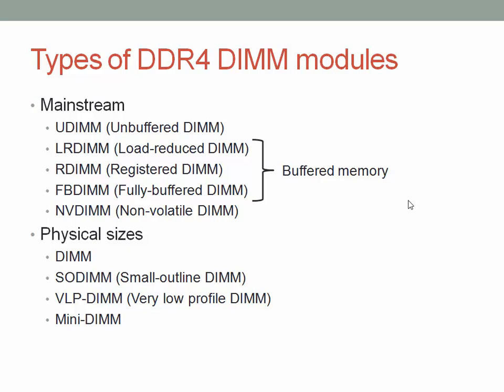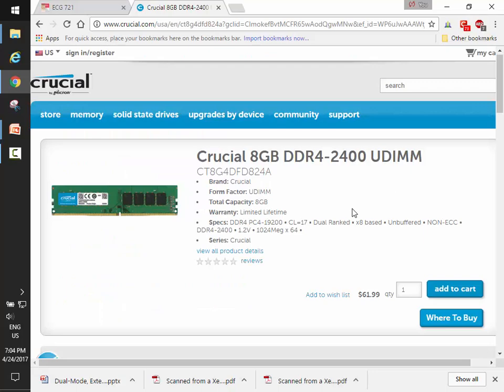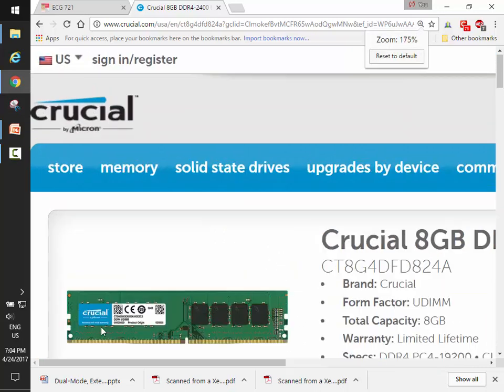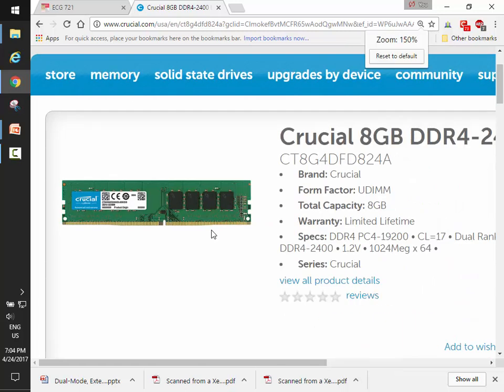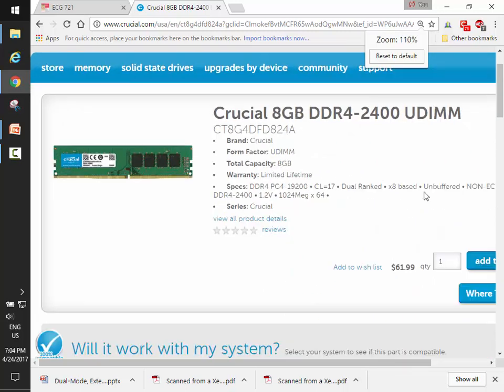That corresponding chip would give the data. You said at the beginning that the DRAM chips were by 8, right? Now go back to the figure on the web page, where it says 64. So that's 64 bits input output.